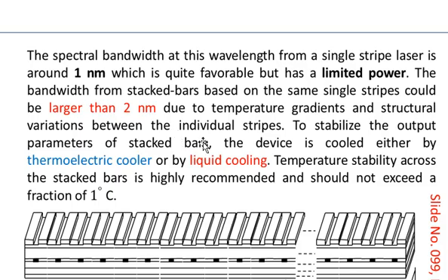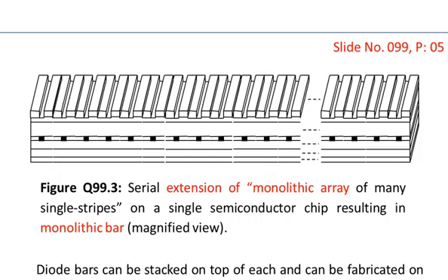That is, we can control the temperature of such a chip either through a thermoelectric cooler or by liquid cooling. And if we can maintain the temperature, then of course we can maintain the bandwidth, and the power stability can also be assured. So you see that I have described